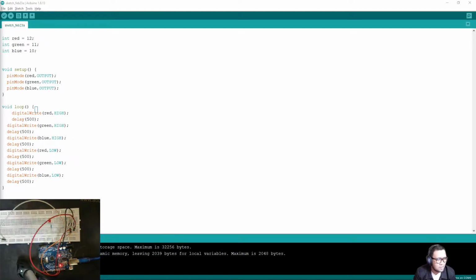So I added an Arduino Uno. Let's just use a small breadboard for this. Let's try recreating the simple blinking one here. As you can see in my code, this is just digital, right? But we will be changing it to an analog signal.